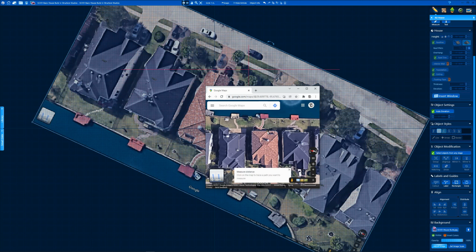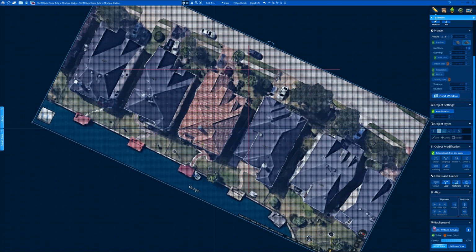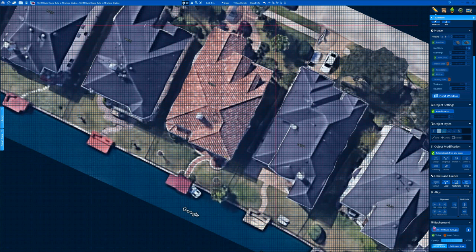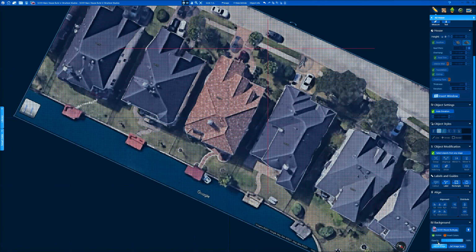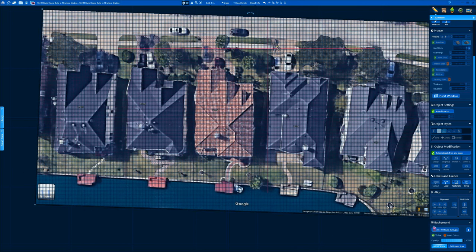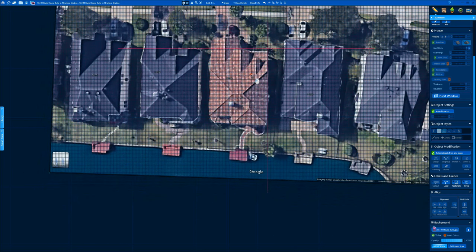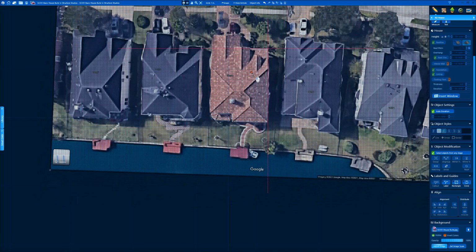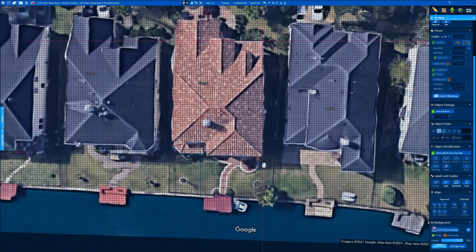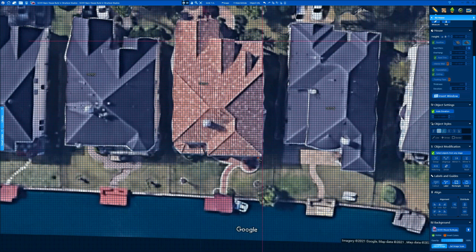It's not going to be accurate, but this is the way that we're going to do it. This does not have a street view. Obviously, I selected a house on Google Maps that is restricted and gated. So let's get this thing squared up. So we're going to turn off our relative or world angle with the K shortcut key so we can freely rotate this thing. Then we're just going to slide this house up into that 90-degree corner right there. And then we'll make some minor adjustments as we move along, just to make sure that we get everything squared up. So we're going to delete that. We're all squared up. Now let's move on to scale.